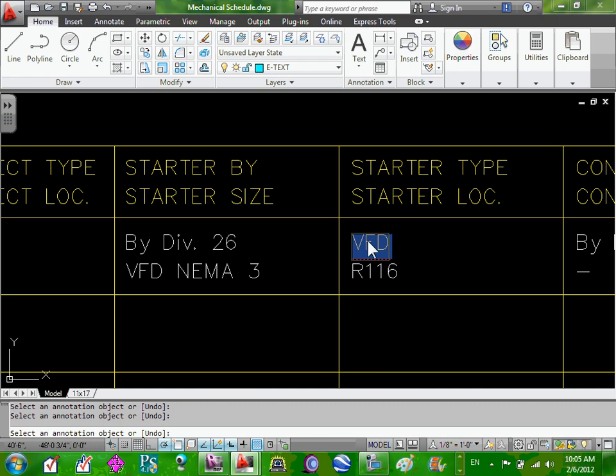It doesn't ramp the equipment up and down to minimize the electrical impact on the grid and electrical distribution system, or the mechanical impact on the equipment. As I said, it's dumber than a rock. Cheapest, easiest. So what are we going to call it? If you have a NEMA, unless they tell you otherwise, it's going to be full voltage non-reversible.